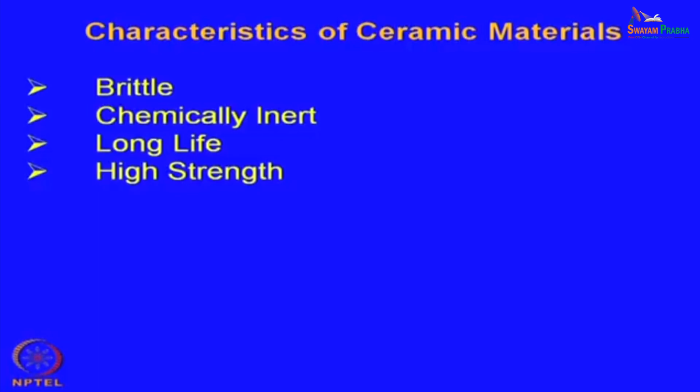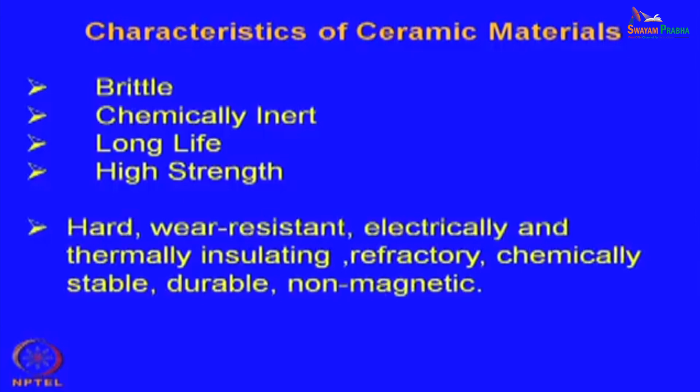So, unlike metals or even polymers, ceramics have this kind of weakness, although they are very strong under compressive load, they cannot be bent. Then the brittleness comes in. In addition, they are hard and therefore wear resistant or abrasion resistant. They cannot be abraded, they can abrade other materials.